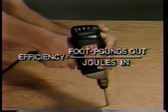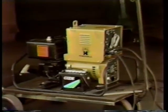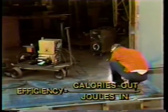To find the efficiency of an electrical energy converter, the energy out is compared to the energy that was put in. Electrical energy in is usually measured in joules. If the output energy is mechanical, it can be measured in foot-pounds of torque. But once again, the units have to be converted so that they're all the same, and foot-pounds can be easily converted into joules. Fluid energy is usually measured in joules. And if the output energy is thermal, it's usually measured in BTUs or calories, which can also be converted to joules.